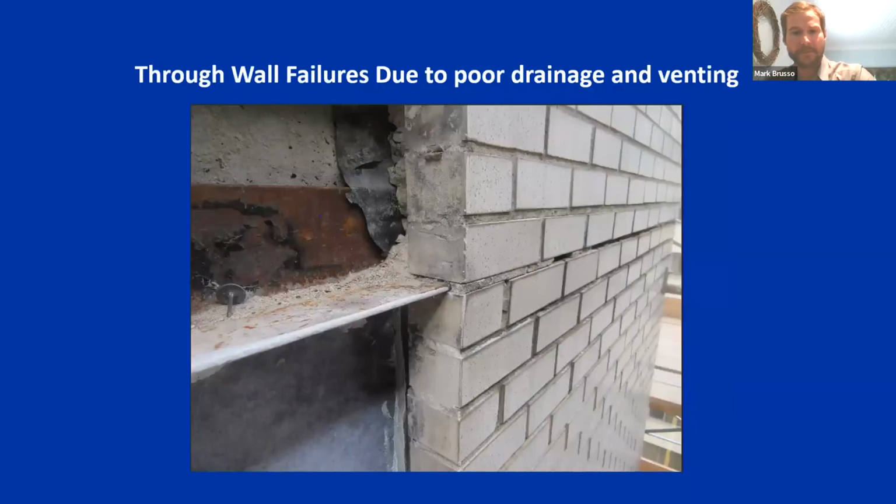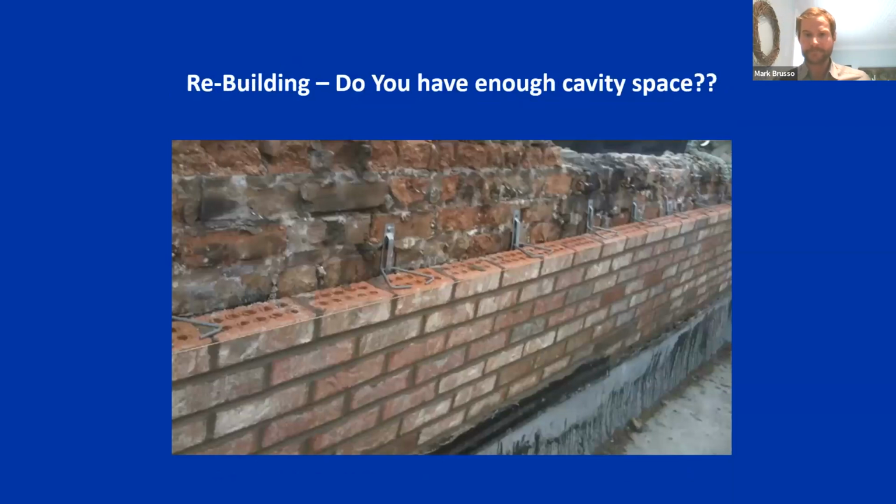Another example of the same thing happening, but with a little better detail of that behind the brick, there is absolutely no space whatsoever for water to drain out. The mortar has completely plugged that through wall area. We're going to show what we can do to improve that issue where water plugs the back of that.